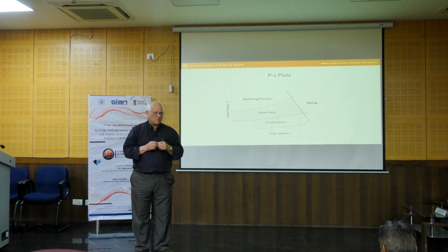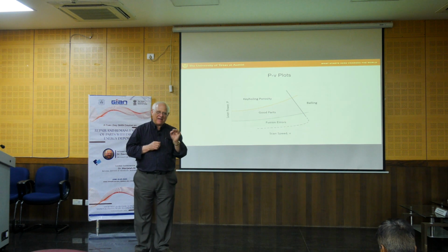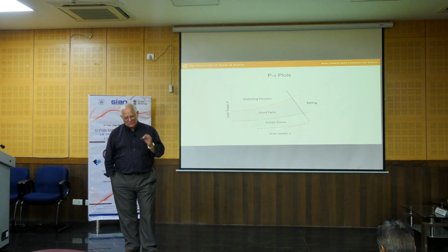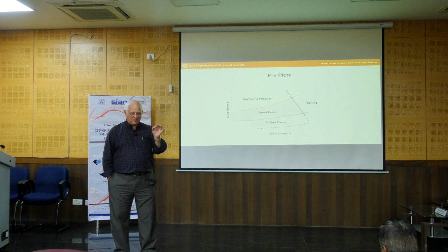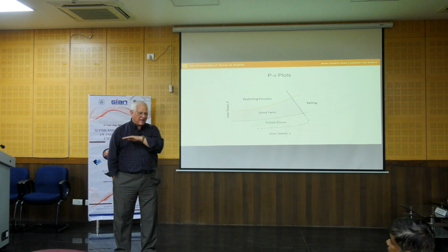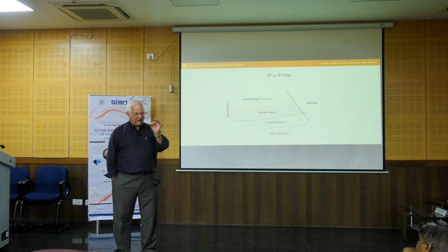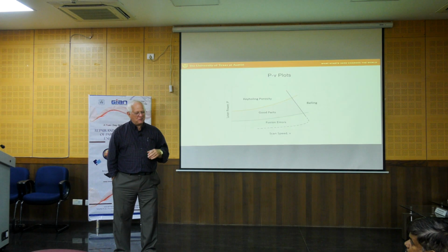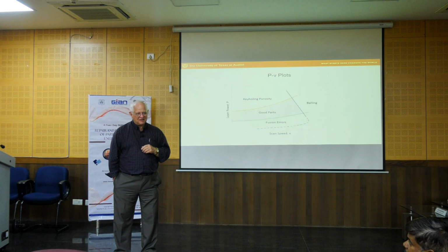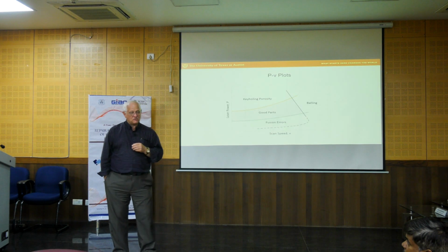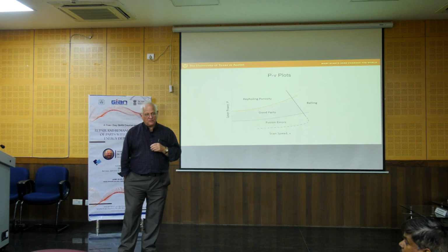Imagine it would be almost impossible to do in powder bed. People have worked with powder bed where you take a little nozzle, you have a matrix material that's the powder bed, then you come back over and deposit material locally, but it's just not very well suited. It's so much easier with DED to do functionally graded materials.